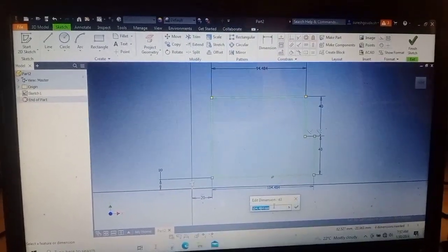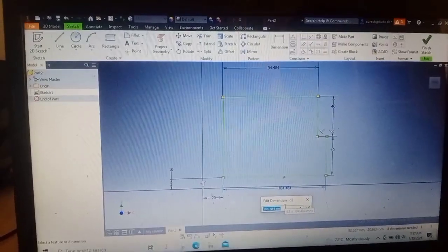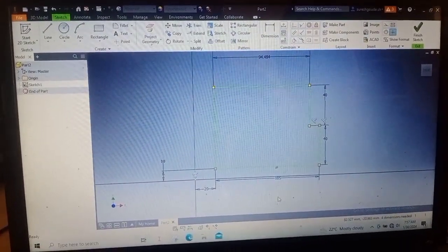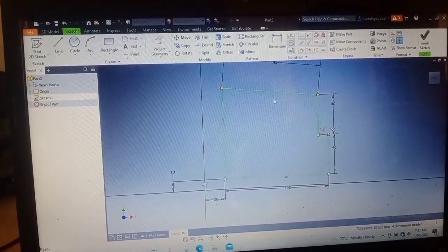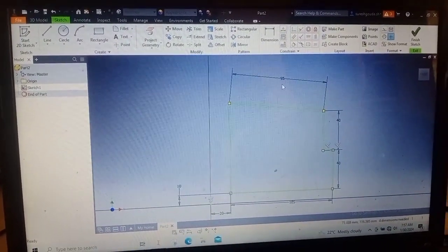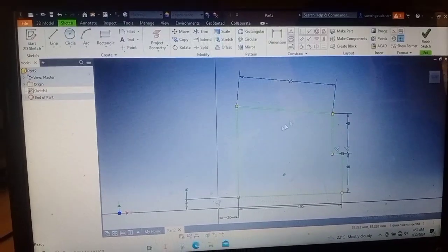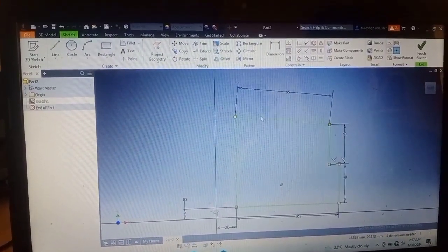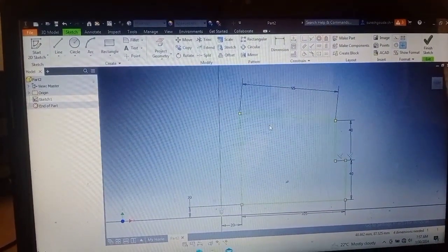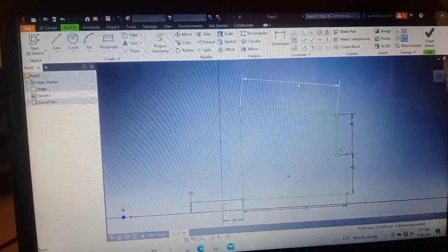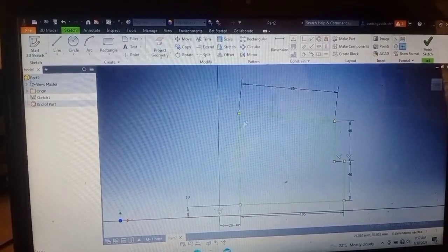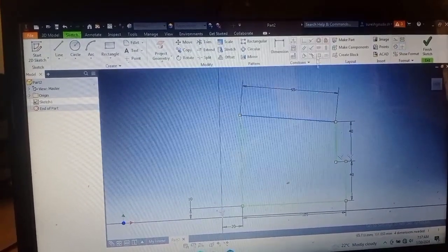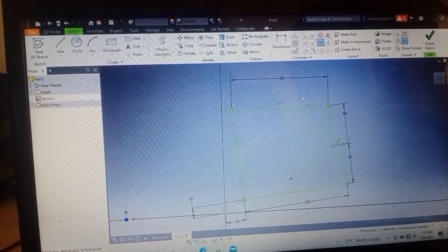And if you want, you can make it round figure 105 and 95. Okay, here you can see when I edited it, the angle got changed. But before doing these kinds of things, we should have the angles of these things fixed. For example, this should be horizontally constrained.